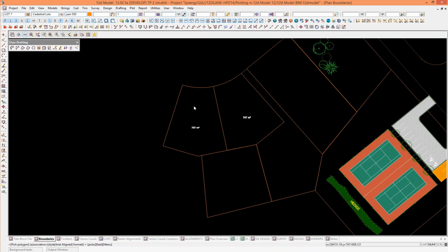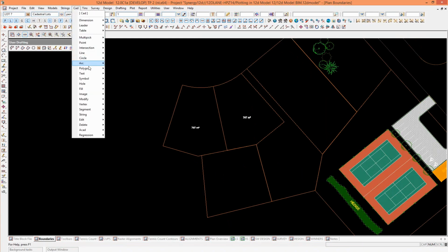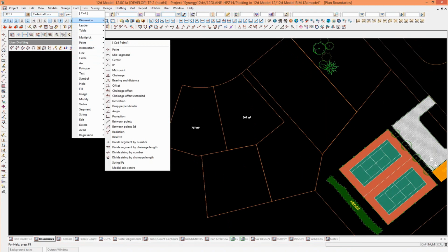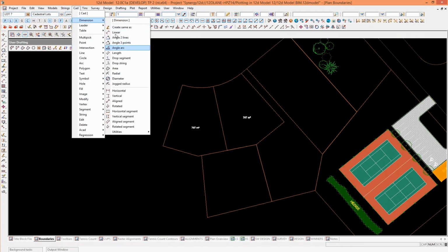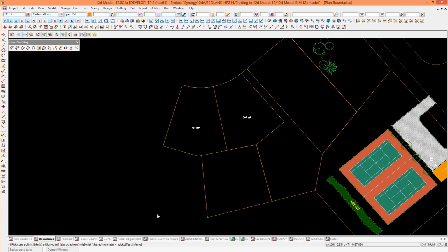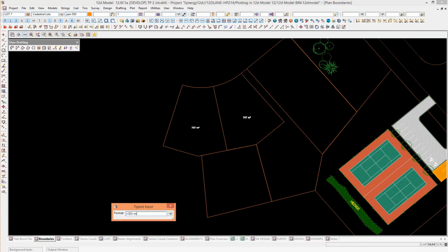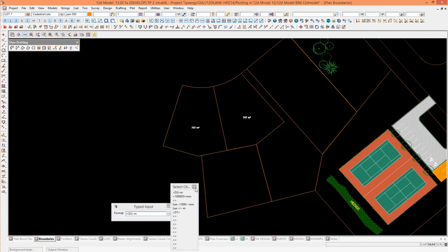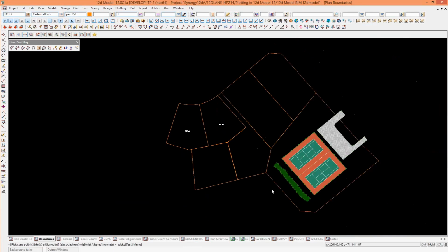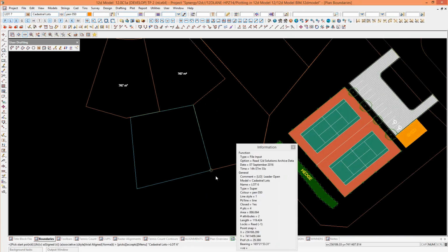The thing with these commands that we're using up here, say if I go to CAD and I do dimension and I want to do a linear dimension, I have to first of all set my style, choose my style. Might want to change my format. I'd have to set my format to the format that I want to use, and then I can create my dimension.